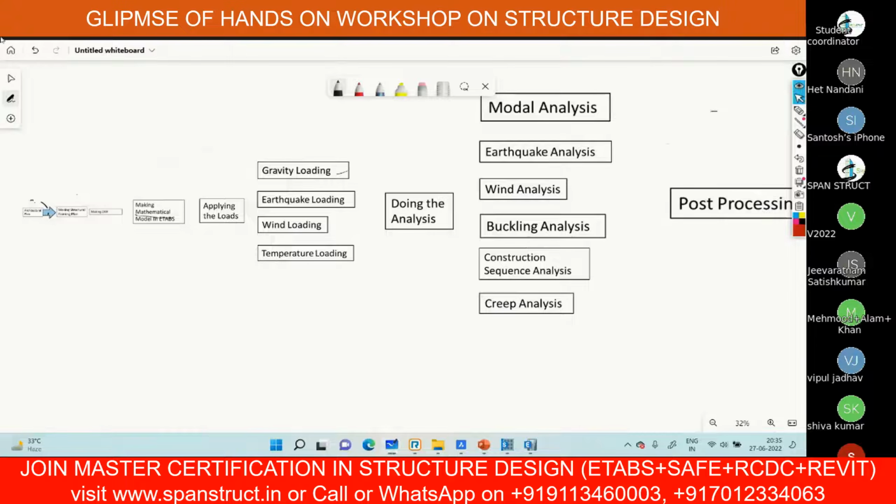So what actually modal analysis is, in this modal analysis you get all the information of the structure. Let's suppose my structure has 20 floors, 10 floors or 5 floors, so I will get a different time period for the different floors. Like a 20 floor will have a time period of 2 seconds, a 10 floor will have a time period of 1 second, and a 5 floor will have a time period of 0.5 second. So when your structure has this much time period, it means that you have given enough mass and stiffness to the structure.